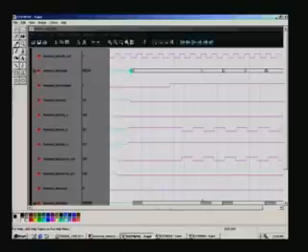That is the reason why it is changing here at every write point, and the address counter is also changing here, 0 here and then 1 here and so on, and it keeps going. The actual RAM is enabled only at this point of time. Therefore, it starts functioning only from this point. In fact, from the subsequent positive edge only it is actively processing.